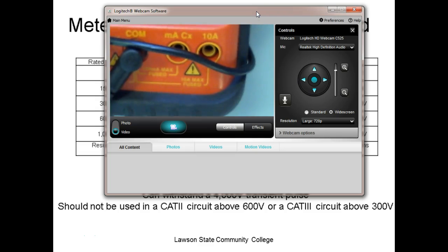If you go to work for industry in the electronic trade or electrician trade, you are going to be dealing with high voltages. Why? Because they got to get that power out to those big old motors. And they're not going to run a wire out there that's a foot in diameter, right? You understand? They're going to step that up. They're going to use like 6,000 volts and make those conductors real small. It really surprises people when you see these little conductors running into these high horsepower motors.